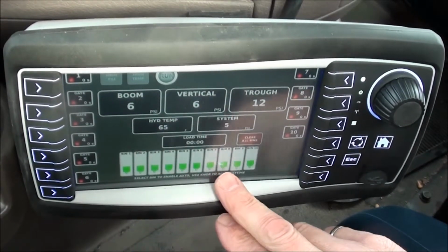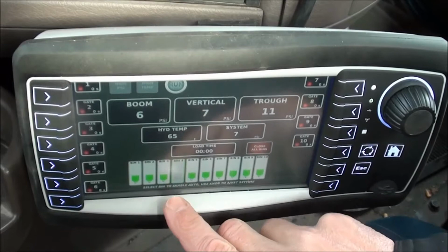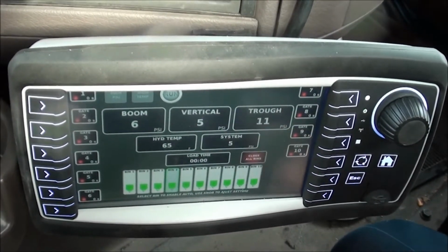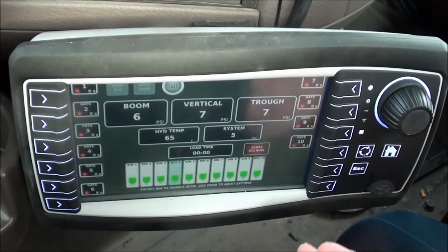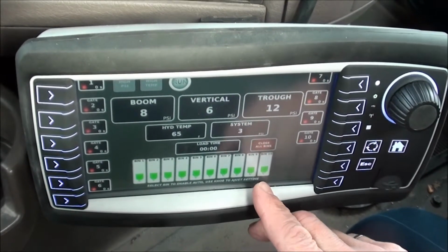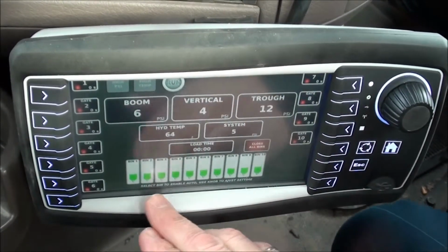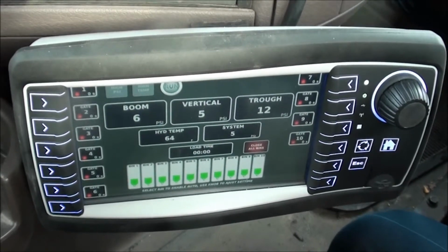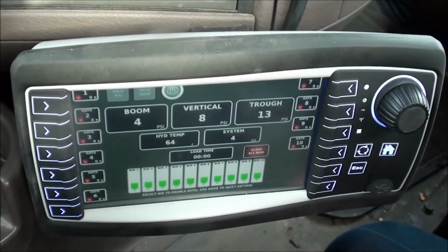This icon row along the bottom lets you pick each bin and activate the bin to be automatically activated, and it's going to use the bin sensor to open each bin as necessary as the one behind it empties out. So that'll automatically open the bins in series at exactly the right time to let the trailer be unloaded one compartment at a time. It opens up the gates as necessary.